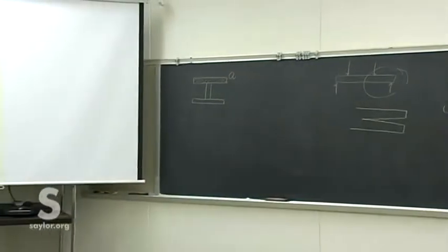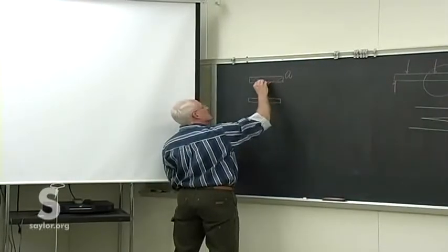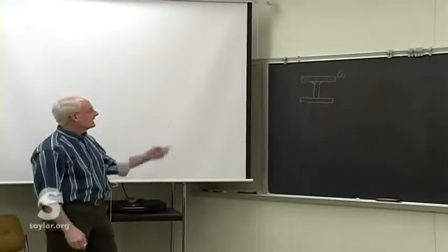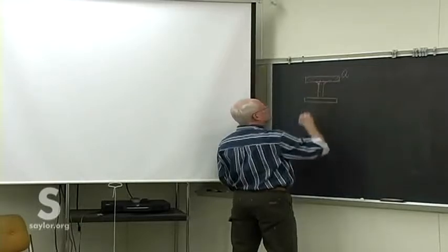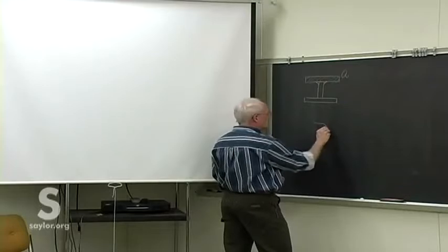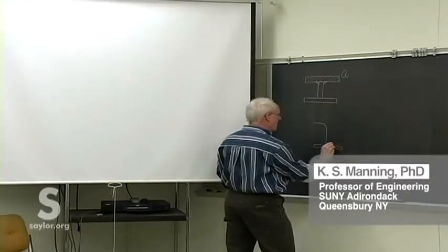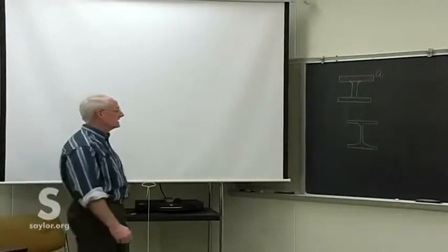If we were making this out of steel plates and we're welding them, we'd run the welds down there, and it's still essentially the same area, because we're still concerned with the area above that plane. If we're taking cast I-beams that are already one piece, most steel I-beams are not made up of separate pieces welded together, they're cast this way.